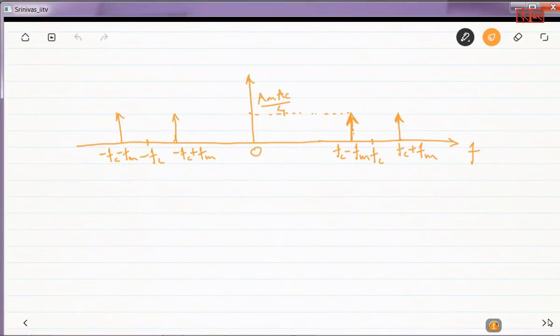So this shows us that simply multiplying 2 signals ensures, in the frequency domain, through Fourier transforms, that we can translate the spectrum. So I hope you got convinced that multiplying 2 signals will do the task for us. It will shift the frequency, translate the frequency range from some low frequency to high frequency.